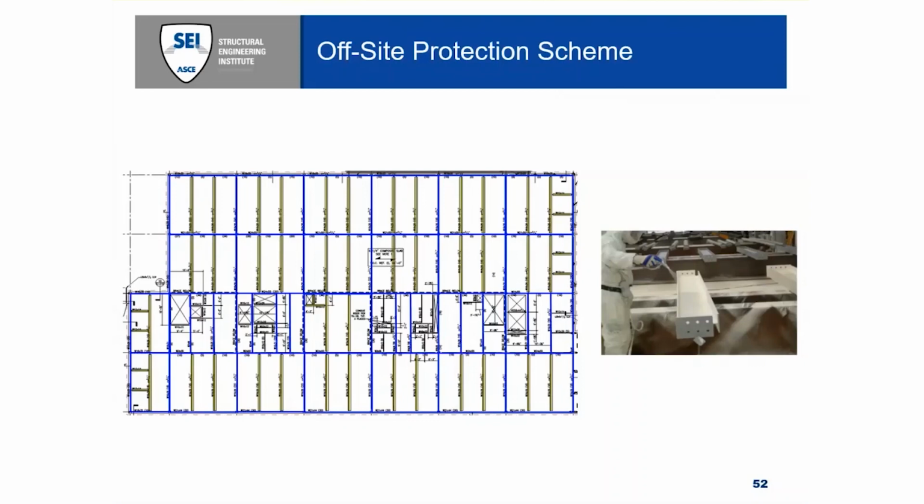So we basically specified the coating under a given fire hazard to limit the deflection of periphery members enough to uphold our slab yield line assumptions. So effectively, this design approach shifts reliance from the insulation itself to the intrinsic strength of the structure to endure the fire adequately.